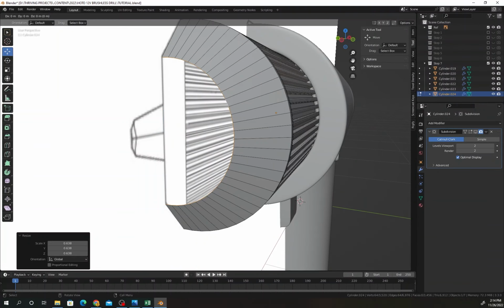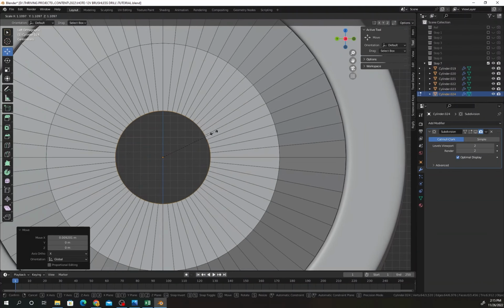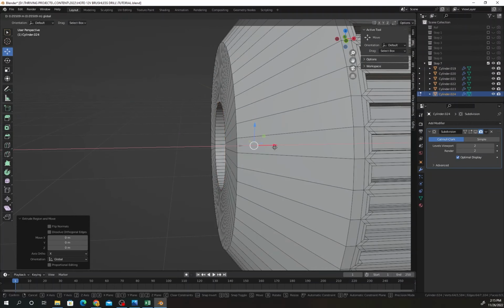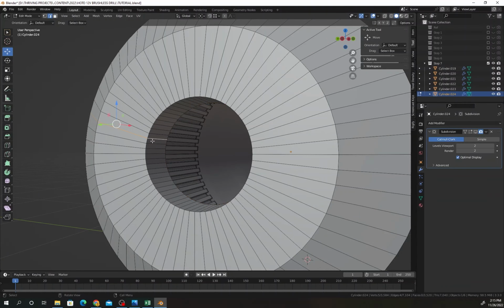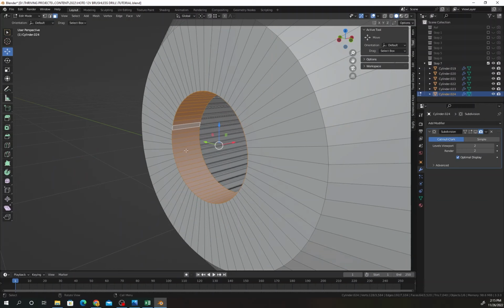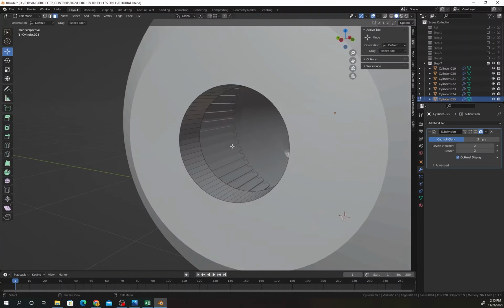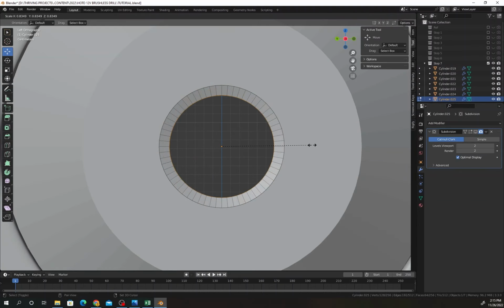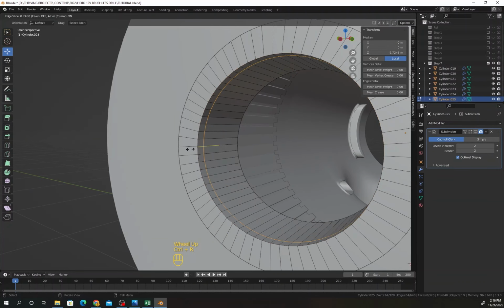Okay, press E S one more time. I will turn off the reference image, press S to scale this up a little bit, then press E and move along X axis. I will select this mesh, press Shift D to duplicate and separate the selection. Then select the separated selection, press E, S, press Shift X, add some support loops here.